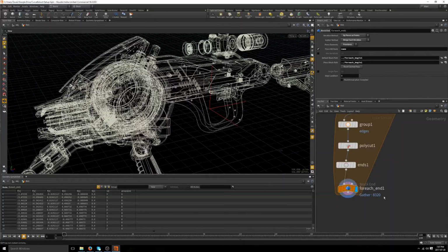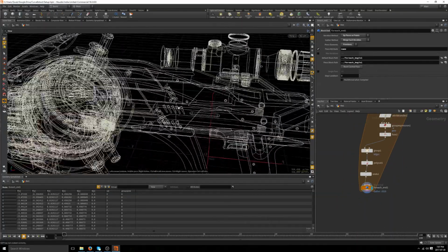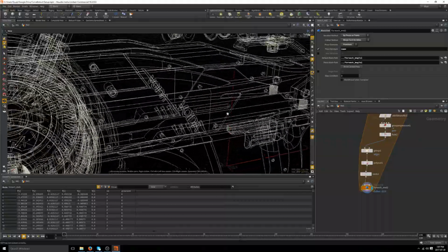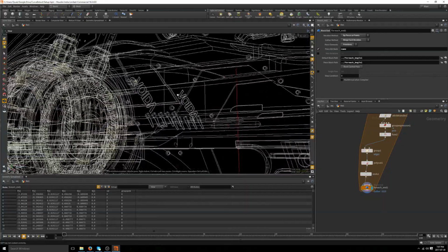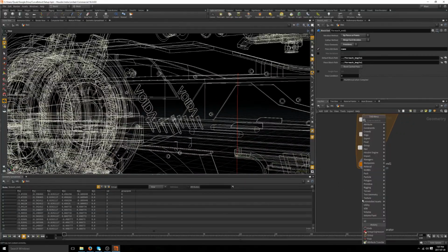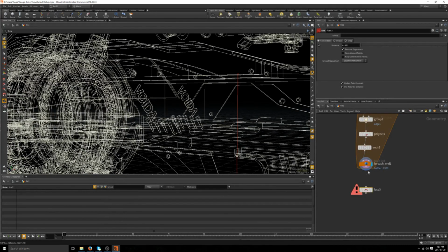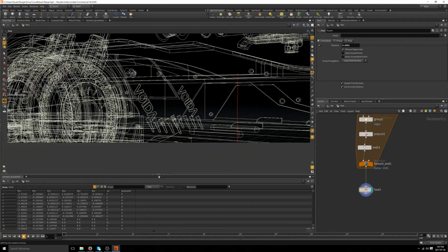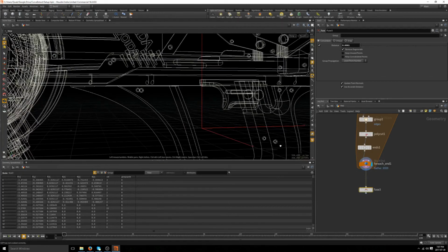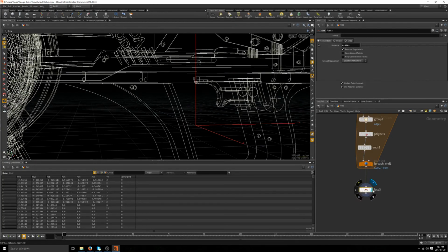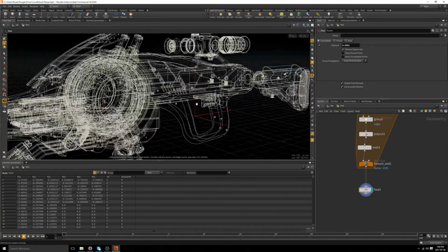So that's mostly it. Of course, because we have processed patches one by one, we have a lot of overlapping edges and of course overlapping points. So we need to merge that together again. First we're gonna merge all the points, again with a very small radius, with the fuse operator. So we switch from 300,000 points to 169,000 points, so that's already good.